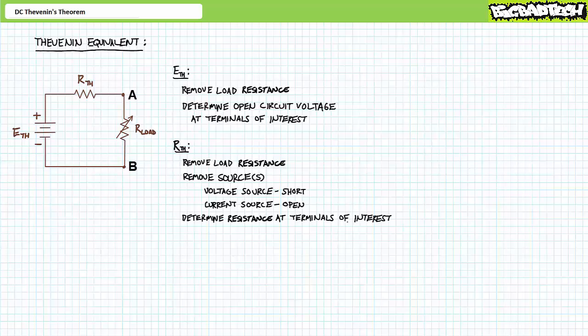using two separate steps. Before we even begin discussing procedures, let me make something absolutely clear. It's all about perspective, and sometimes shifts in perspective mean different things. You can solve for ETH or RTH first. Order doesn't matter. However, you simply must understand ETH and RTH have nothing to do with each other and are never, ever used to solve for each other. Only in the Thevenin's equivalent circuit do they come together to create a pure series circuit, which should ideally behave identical to the original more complicated series parallel circuit, with a notable advantage of being easier to build and analyze.